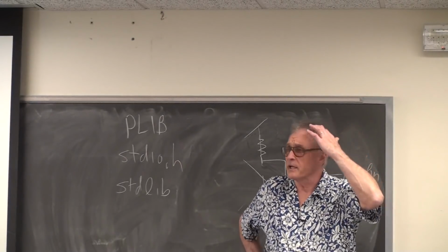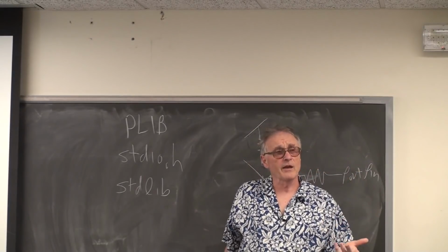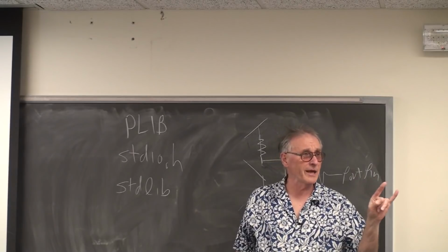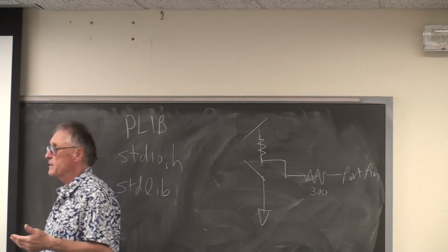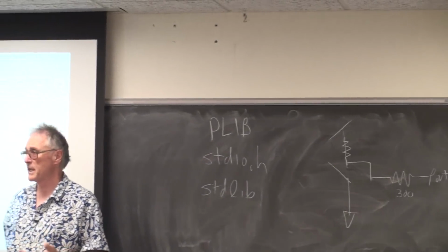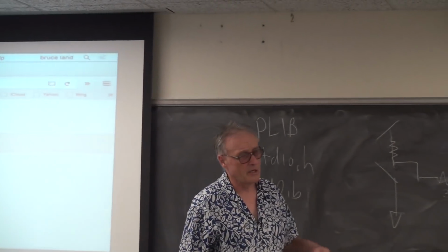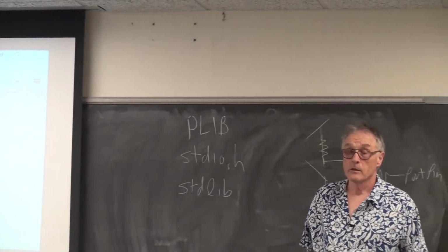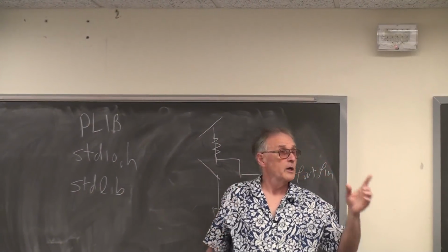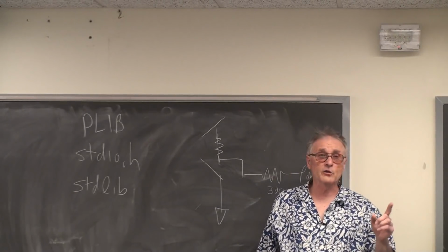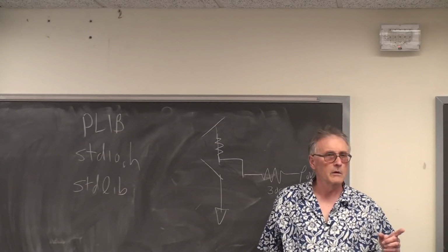There's an internal oscillator on this chip so that you do not have to have an external crystal. If you want high timing accuracy, you do need the external crystal, because the internal RC oscillator is only guaranteed to 0.9%. It's good enough for most stuff. In addition to the internal oscillator, if you read the oscillator section of the hardware reference manual, which, oh my goodness, that's a piece of work, there's a phase lock loop built in. You know what a phase lock loop is? Everybody know what a frequency multiplier is?